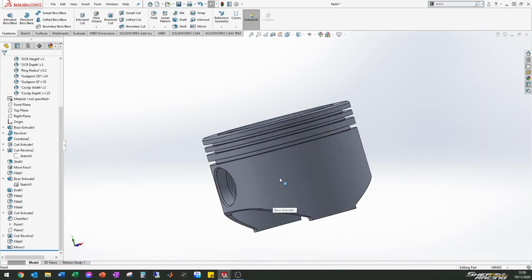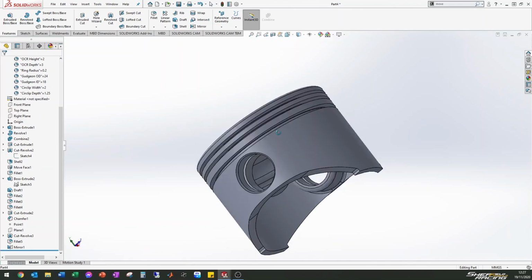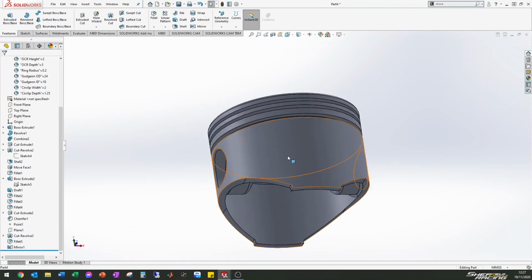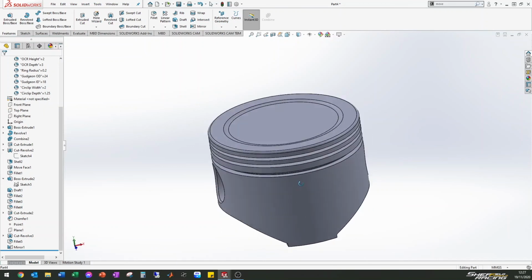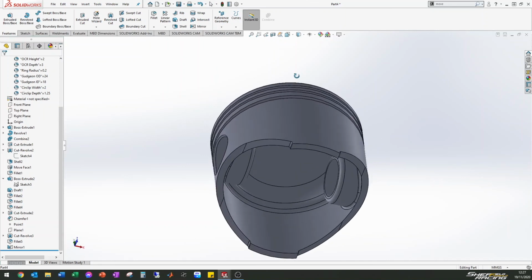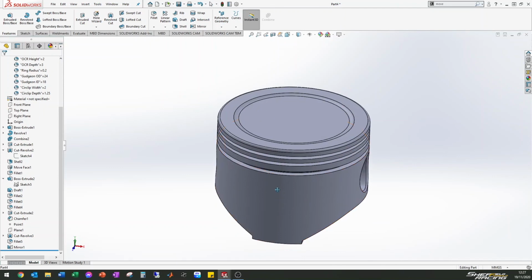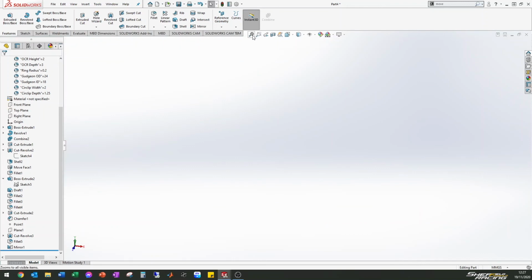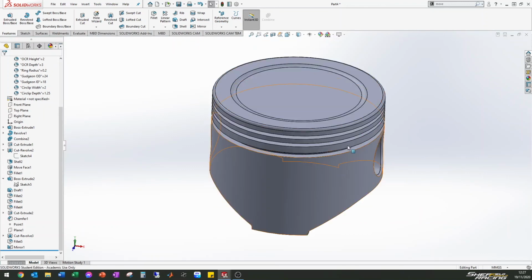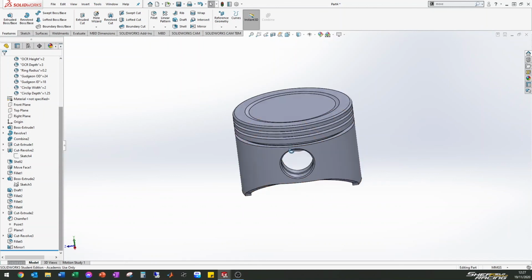So we've covered quite a lot there. You will get used to things like rotating the part around in the window. To do that, you click the mouse wheel. One thing I'd recommend is having a proper mouse and not using your trackpad on your laptop. And then if you want to move it, if I click Control and the middle mouse wheel, I can move it around that way. If I zoom into the wrong part, I can click this button here, which zooms to fit. That's a helpful tool. But the main thing is just practicing. You will only get better at SolidWorks by practicing.